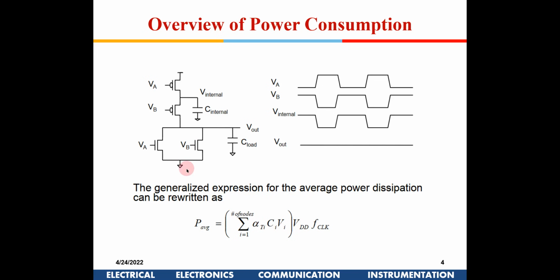Not just inverters. Now we are not talking only about inverters, but any circuit. So we will have to see which nodes have switching, and accordingly take the power of all those nodes and do a summation of the powers of each of these nodes. Okay.